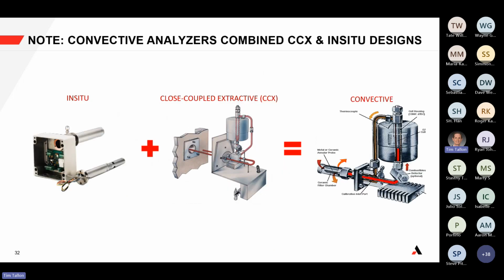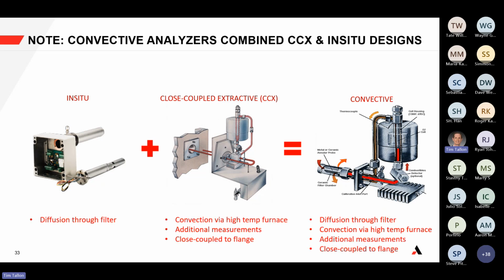And if you were to trace back to its roots, the convective analyzer is actually a combination of the elements of an in situ and a close-coupled extractive. I alluded to this in the beginning, but what you can see is that it brings the concept of diffusion through the filter, like it would be in an in situ, with some of the advantages of a close-coupled extractive design.